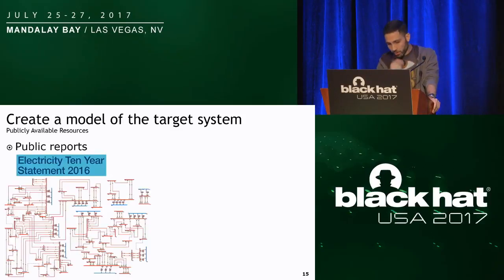A particular report that we found online has a detailed representation of a country's transmission network topology, along with the transmission system dataset. For example, it had the kV and MVAr ratings of generators, transient synchronous reactance, transformers' leakage impedance, types of cables, and even 3-phase and 1-phase short circuit levels at peak load conditions.